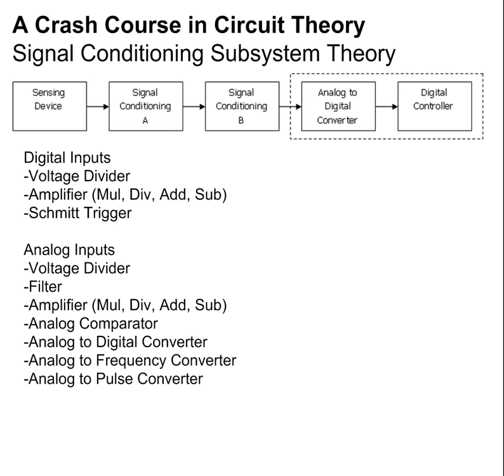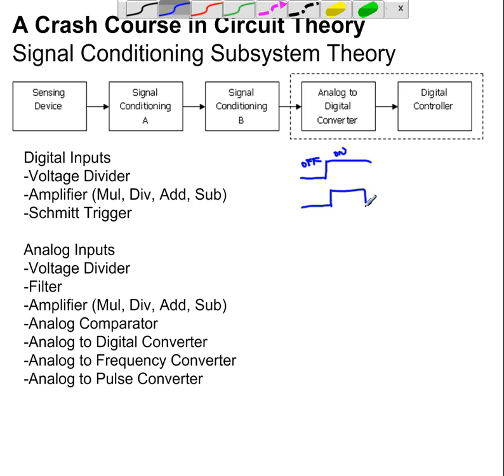Remember, the microcontroller can accept many types of digital signals. Of course, it can accept the normal on-off, but the microcontroller can also read advanced signals. It can read the width of a pulse. These are normally used by ultrasonic sensors. It can actually read the frequency of a periodic signal. You can write a program to measure the frequency.